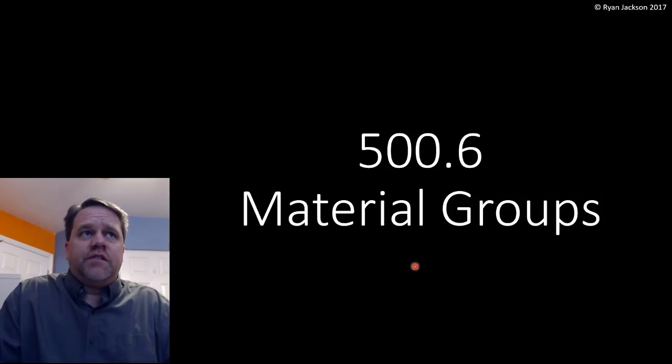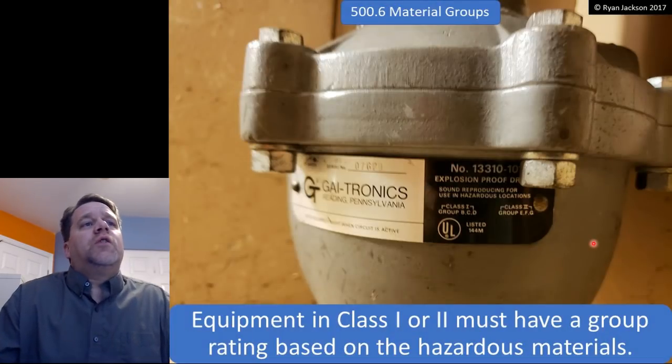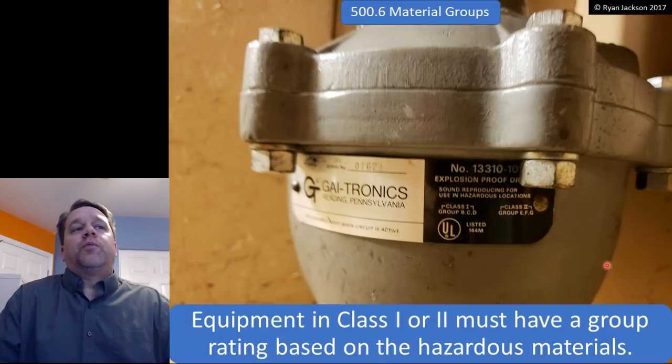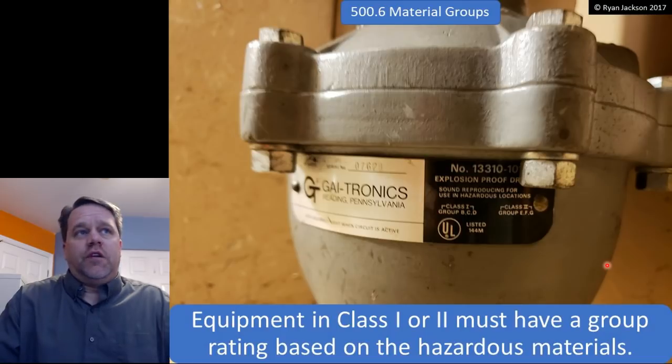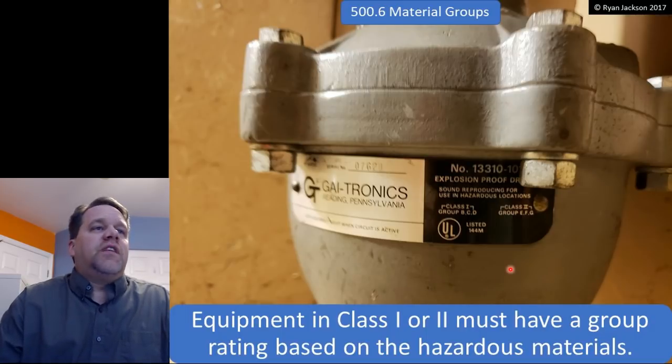500.6, changing gears ever so slightly, we go into material groups. Equipment in a Class 1 or Class 2 location must have a group rating based on the hazardous materials. Right off the bat, we can see that this does not pertain to Class 3 locations. So Class 1 or Class 2 must have a group rating.